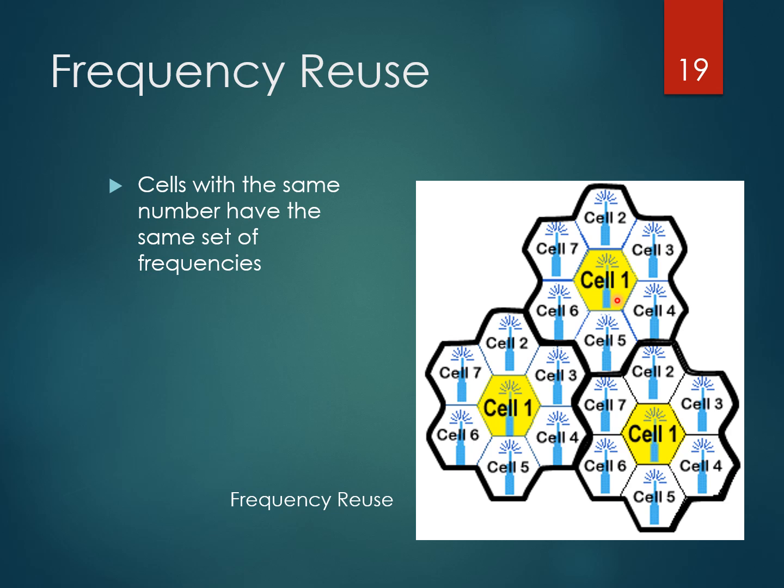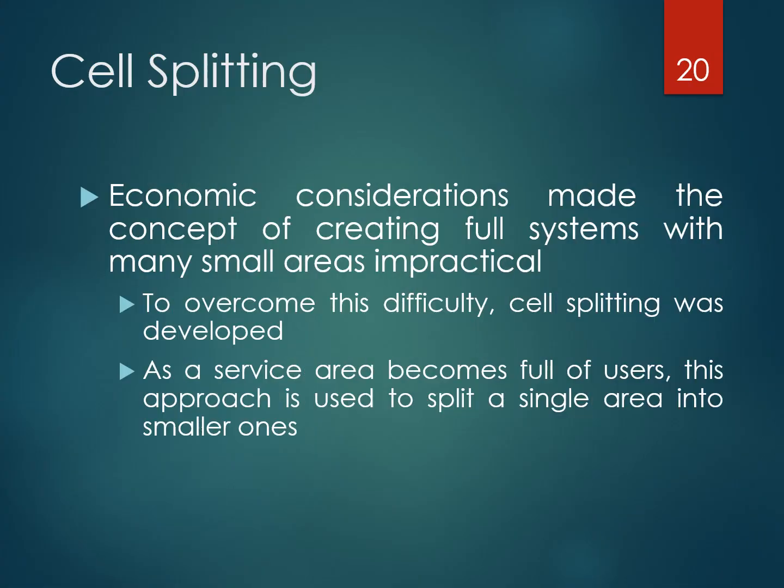Cell 1 and the center point, the distance you can utilize should satisfy a particular logic that I will explain again. Again, the same 850 to 950 megahertz frequency can be utilized in this cluster also. So in this way, you can use your frequency reuse.